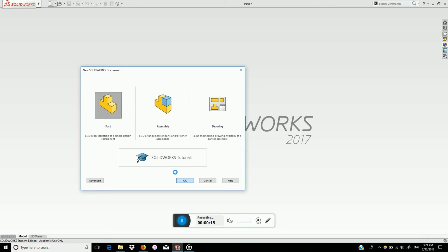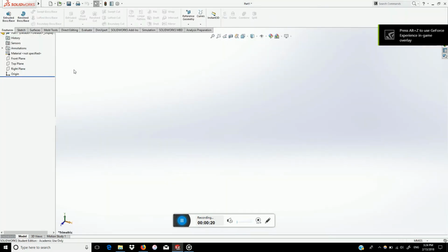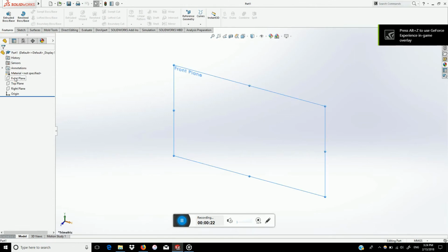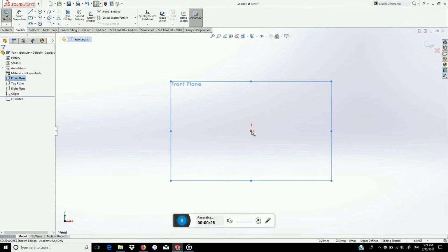It can be a flat face of an object, or one of the three initial planes, or a newly created plane. After you select your plane, you will see the origin, the point that is always the center of the plane, and indicates the horizontal and vertical directions. It is a good idea to start all your sketches from the origin, since it will always be fully defined. Now you can start sketching.